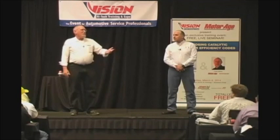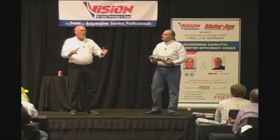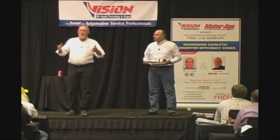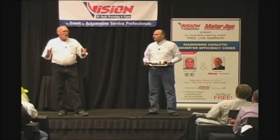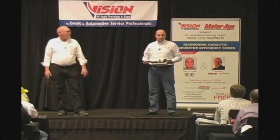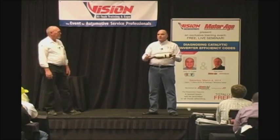But today I want to stress that the universal catalytic converter that a lot of manufacturers offer doesn't mean quite the same thing. You know, they're still certified to the car that they're being sold for. The universal only means that they don't have the plug that you can cut it out and put the new piece in. Bottom line is, if you're getting your components from a good source, a known good source, you shouldn't have a problem whether it's something that you weld in or that you buy as OE fit. So basically you'll get a piece like this that is a good converter, but all the components or pipes or flanges will be something that you add on.